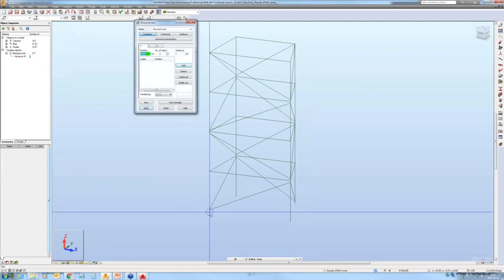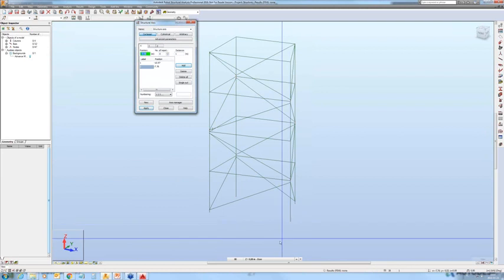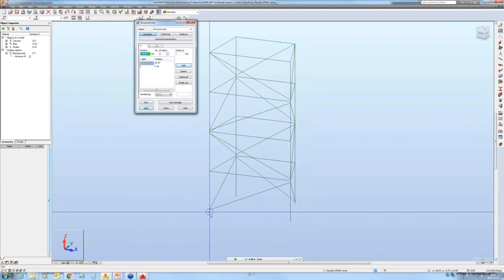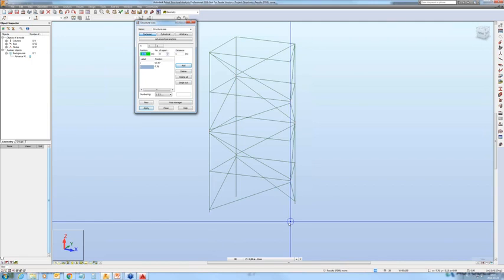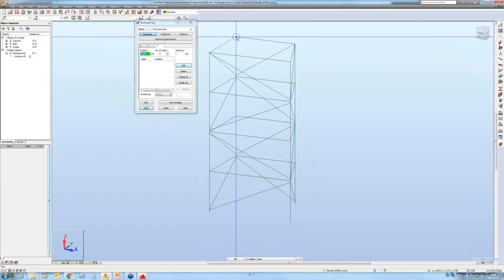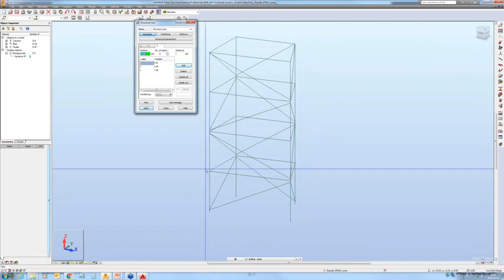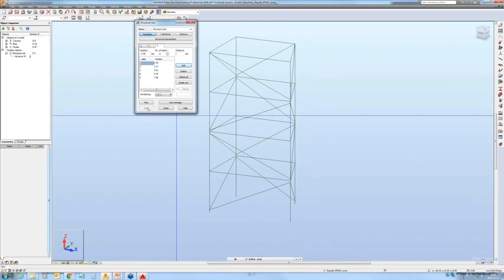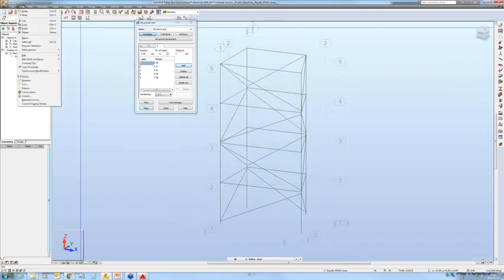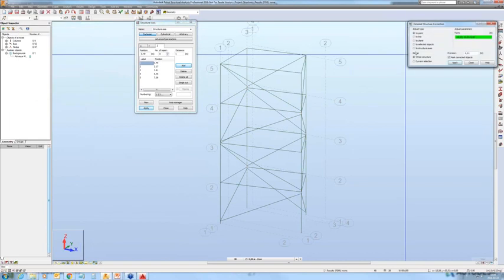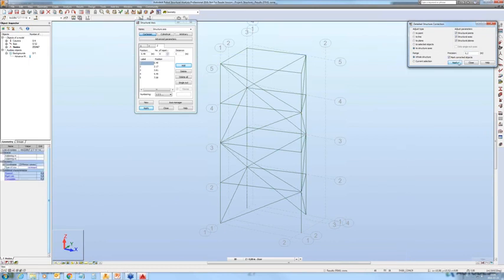Okay, let me click on Nodes, and then I will create Y-axis and Z-axis. Okay, I can press the apply button, and now I can use edit and detailed correct to structure axis and specify the distance, and when I press the apply button I can merge the nodes so that I have the correct analytical model.